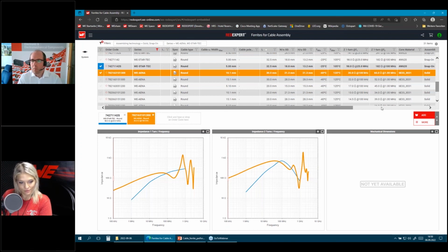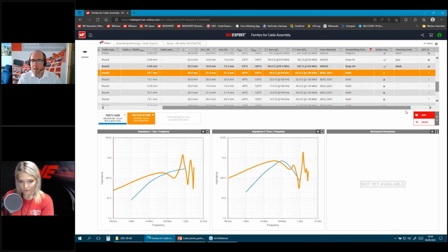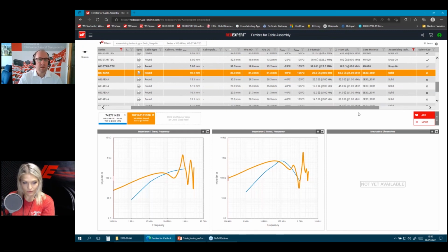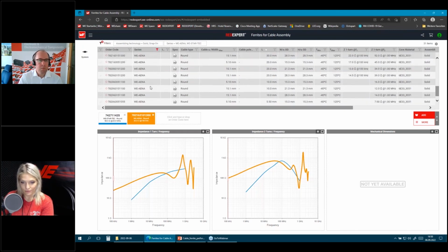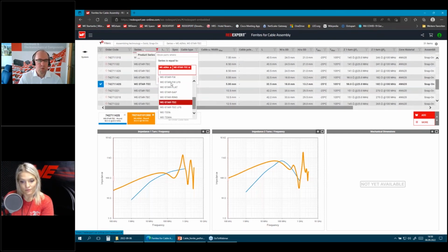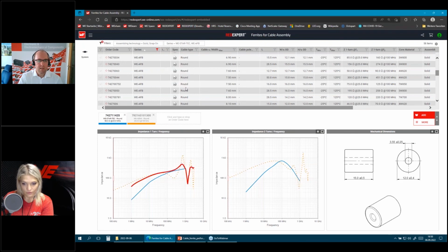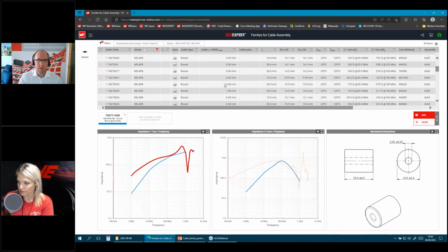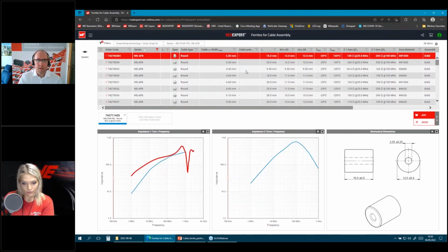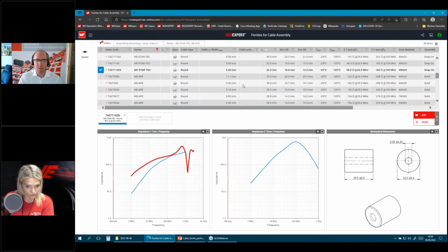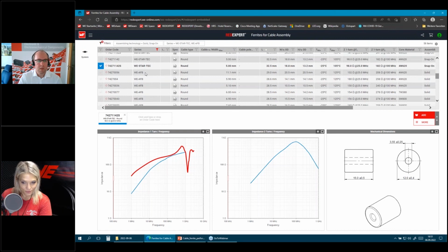And is it also the same material? Not quite. Yeah, okay, the nanocrystalline material here is a bit different. So maybe I should select components which have the same material, which is nickel zinc in this case. So let's delete this one again and see if we find a similar component which has a similar length, but yeah, that one.